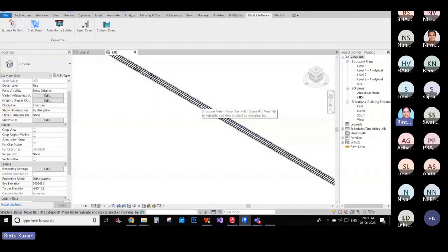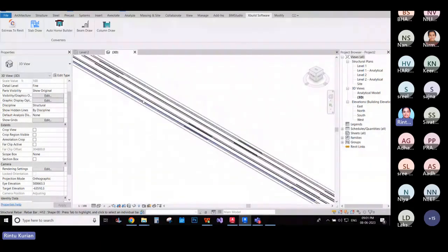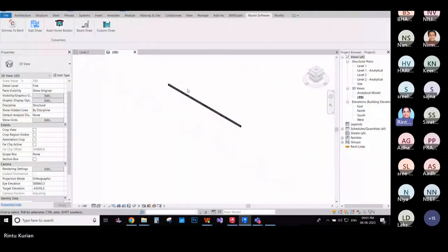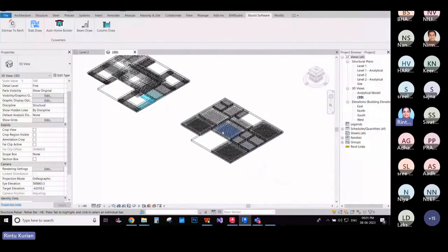The regular ones like the common beams, columns, slabs and so on can be generated using plugins. That will be the easier method. So with this, bringing the BBS into 3D is wound up. We'll have the session for column rebar when column BBS is being taught. And I'll demonstrate the Estimax to Revit plugin when we have the session for estimation.